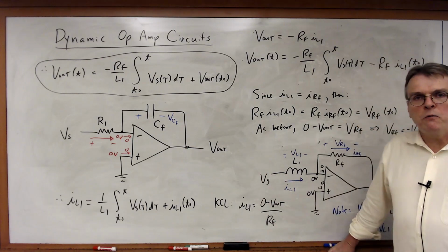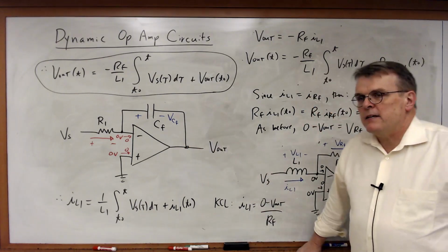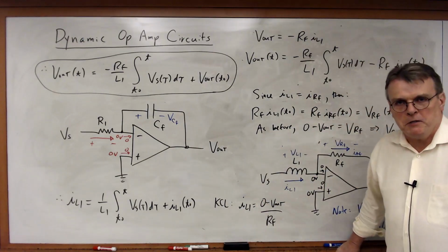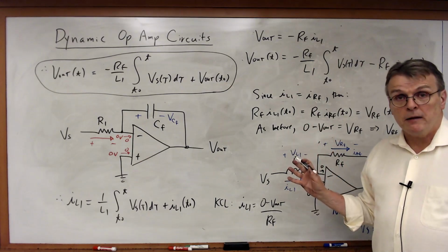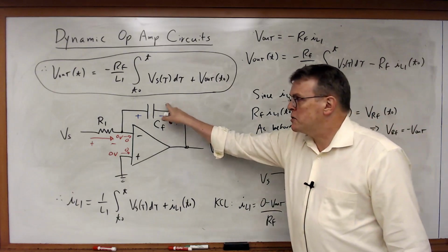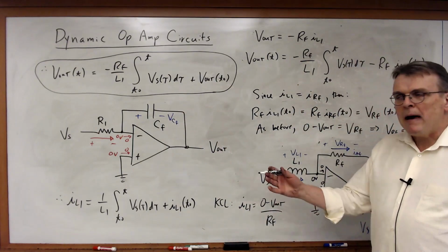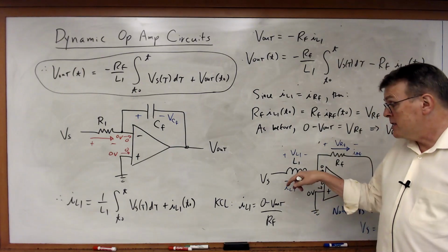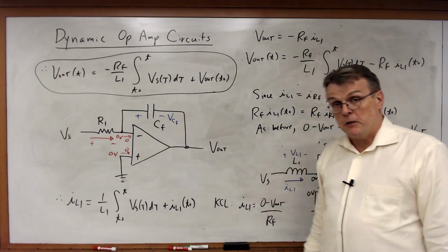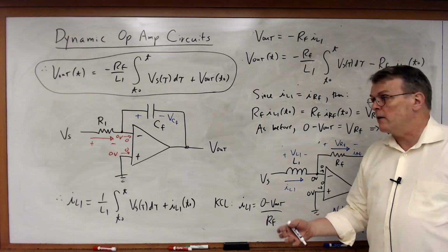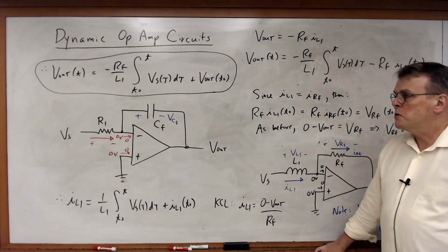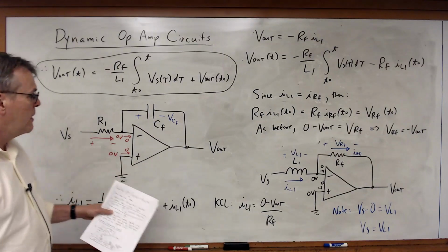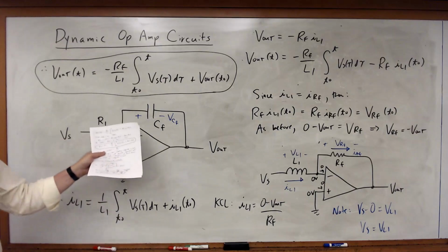Now, here's a question for you. Since both of these circuits do exactly the same thing, is there any reason why we would favor this circuit over this one? Well, turns out there's a very good reason. Although functionally both of these circuits can be made to do the same thing, it comes down to economics. Capacitors are much cheaper than inductors. A capacitor is just two metal plates side by side. A good inductor typically requires winding a coil of some sort. It's not something you can really integrate on an integrated circuit, but capacitors can be placed on integrated circuits. So from a viewpoint of manufacturing on a large scale, capacitors work much better. They're much more economical. So even though these are two equivalent circuits from a mathematical point of view, from a viewpoint of practice, we never use the inductor version. We use resistors and capacitors to create circuits like this.